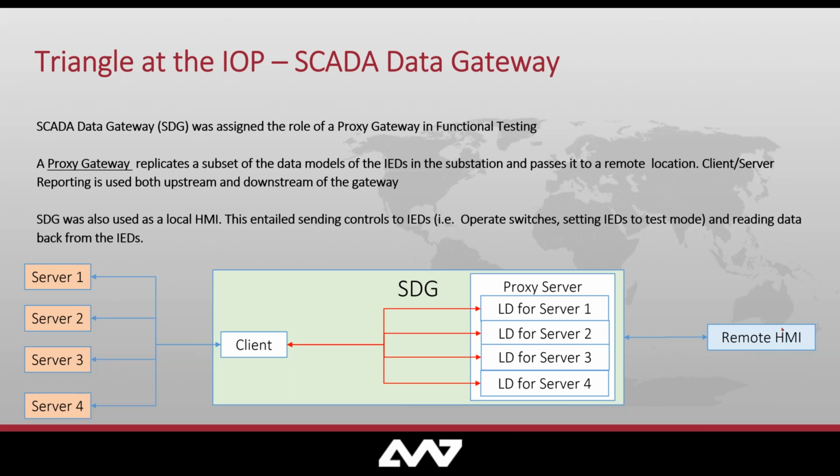If you look at it from that perspective, one of the reasons is just to have fewer associations required from the SCADA system down to the IEDs. We only have to associate to the proxy server instead of to all the individual IEDs. Then the other point is, in principle, we can remodel the data structure a little bit. So you can make a more device-architecture-neutral data model in the proxy server. That's a possibility, so that you don't necessarily reflect one-to-one the models from the devices.